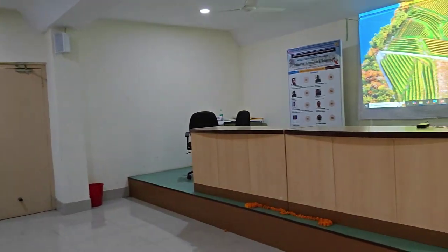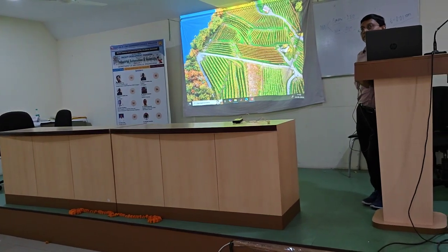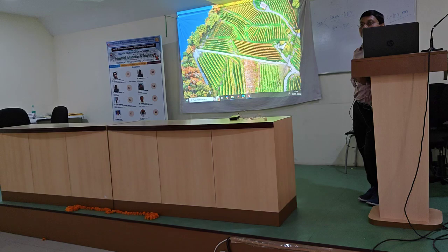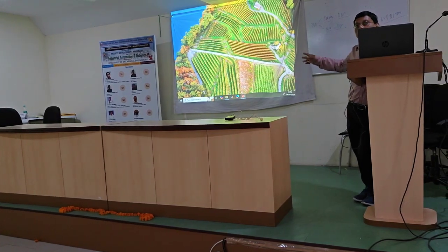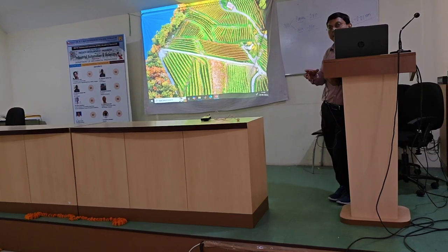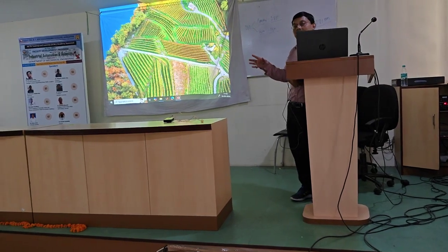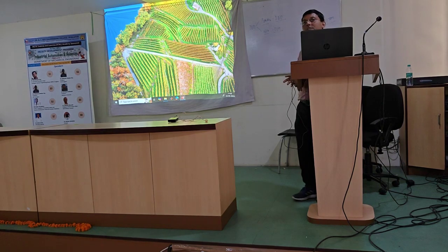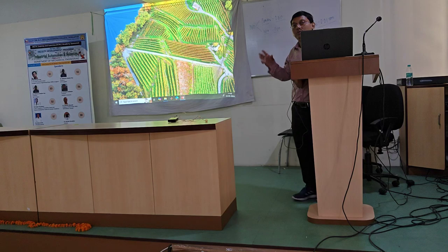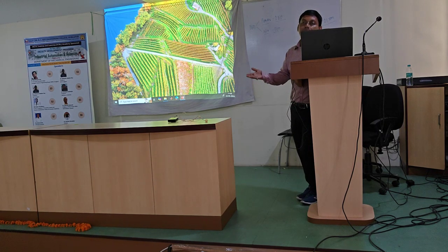Accuracy suffers, and heat dissipation is not controlled well, so that is why you are also not getting strength. That is a big issue. In 3D printing, even with powder, whatever strength you get is much lower than any product you develop by traditional manufacturing, because that issue has not yet been solved. That is why worldwide metal 3D additive manufacturing research is working in that area: how to control the heat dissipation and how to improve the mechanical and metallurgical properties of the product. This is a very important research area in additive manufacturing.